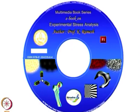Then you have strain gauges, photoelasticity. So, all the conventional methods which are time tested come in this category, and in this you find the use of Moiré interferometry for finding out crack tip stress field equations. And I have been saying that you have to use phase shifting methods, and this is the spanner where you find these are not fringe patterns, these are phase maps.